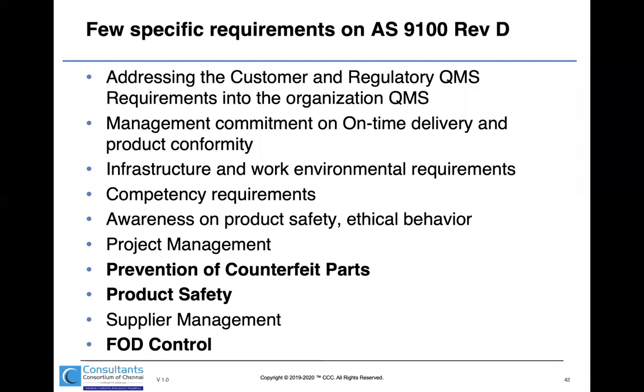But please stay connected. Then competency requirements. Of course, there is no specific additional requirement with respect to competency, but what IAQG wants is that we periodically review the competency requirements. Most standards say determine the competency needs. Yes, of course we determine, but we need to periodically review it, because industry standards keep changing. Yesterday NDT personnel should be qualified as per ASNT, and today the industry standard may call for qualification as per NAS 410. So we need to periodically recheck the competency needs based on customer requirements and regulatory requirements.